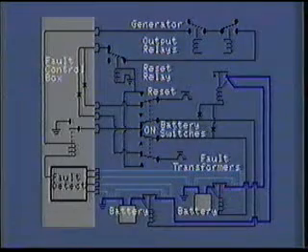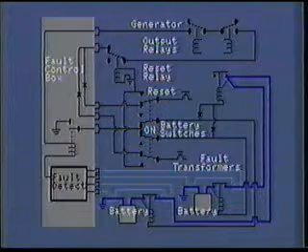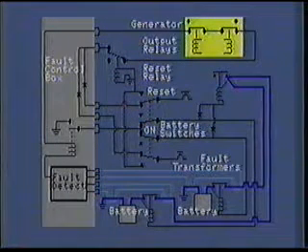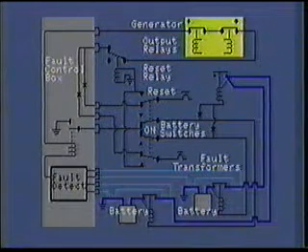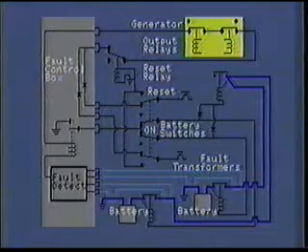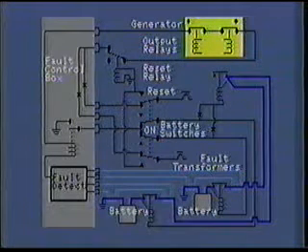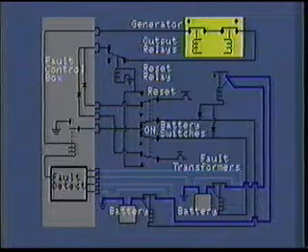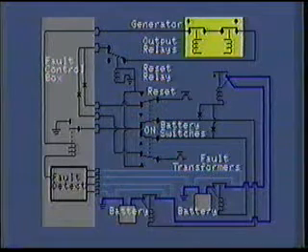If this occurs, the pilot would attempt to reset the batteries. The reset sequence is as follows. After the engines are operating and both generators are placed online, that is, providing power to the bus system, a condition needed to arm the fault protection circuit, two generator output sense relays will close.